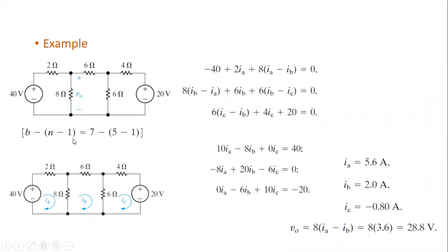Okay. Now, once we have examined the circuit, let's see how to solve it. First of all, we need to assign the mesh currents. So we use this mesh, and this mesh. As you see, you need to select the loops which have no loops inside them. This is very important. So we don't use this loop, we don't use this loop.